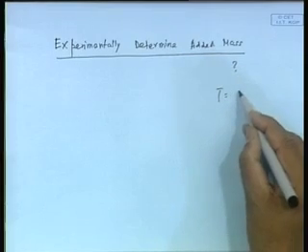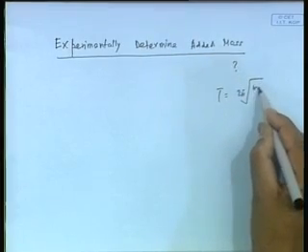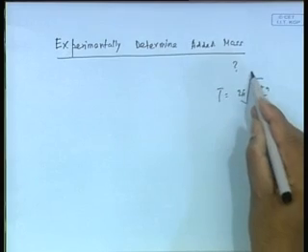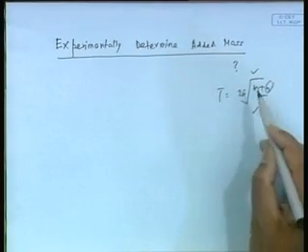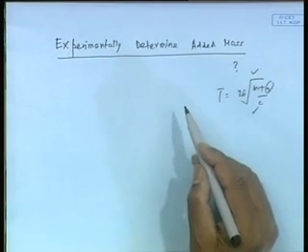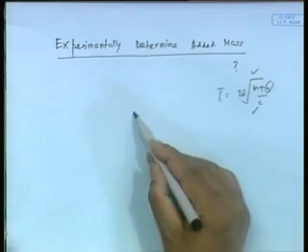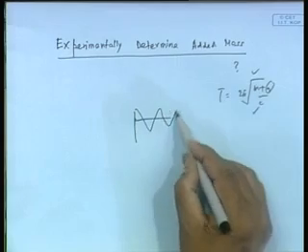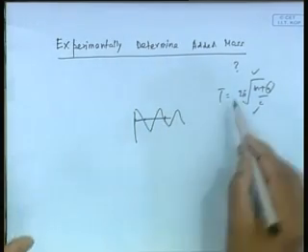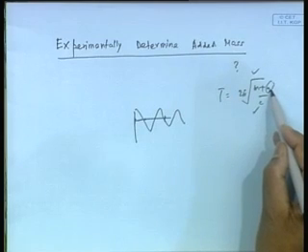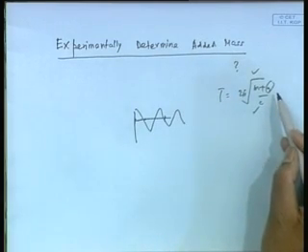Point 2 is that, see, I know that this T equal to natural period equal to like 2 pi into square root of (mass plus added mass) by C. Now, here I know this for a geometry, I have to only know this added mass. So, if I were to take a body and just push it down, it might go like that. So, I can figure out this period and I can say, well, I know everything, I can find out this. Okay. But there is something wrong.